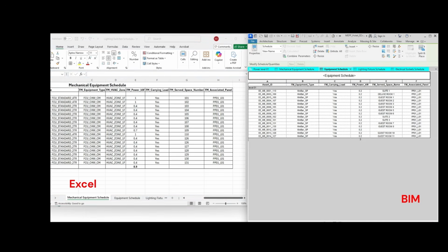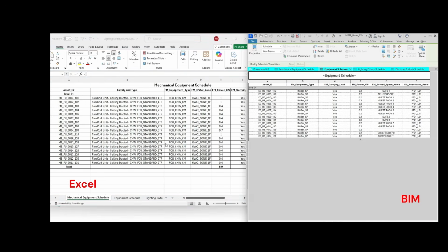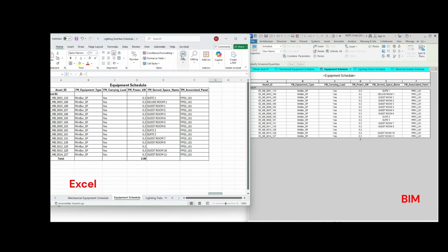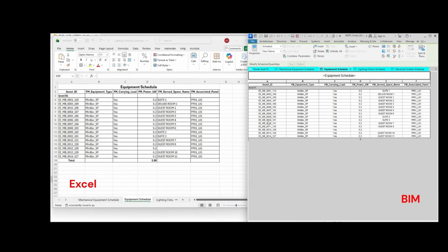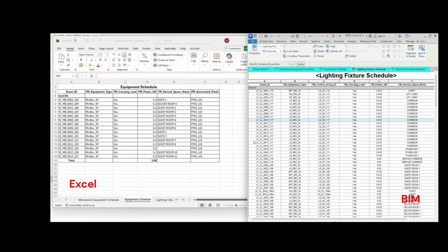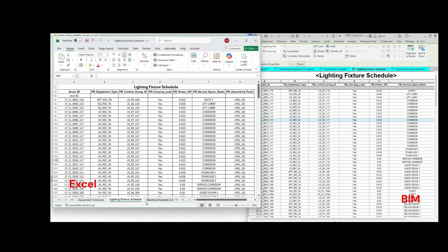FM scope definition. Before modeling anything, we clearly define scope. This series focuses on operational facility management, not hidden services maintenance. Concealed infrastructure, such as conduits inside walls or slabs, is typically referenced during renovations, not during day-to-day operations. So for FM, we model assets inside spaces, connected to panels, with operational data. This single decision avoids overloading FM teams with information they don't need.